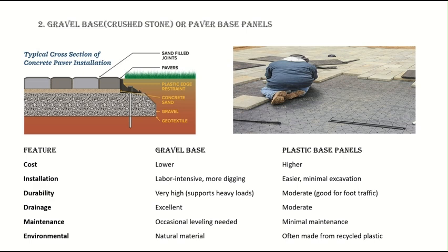But there's an alternative to it. The alternative is plastic-based panels. So we can just simply put these panels on the ground, put some sand on it, level it, grade it, and then we will install the pavers on top of it. So there are some differences in it.